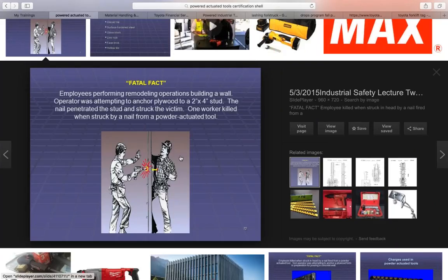Also, ensuring that cranes and hoists are inspected to see that all the components are in good condition, to make sure that they're all compliant, lifting hooks, equipment, whatever the case may be, and then not exceeding the lifting capacity of cranes or hoists. Like we talked about, not only exceeding the capacity, but like I said earlier, anytime we get to the hooks, the slings, the crane itself, whatever the case is, anytime we get over that 75%, like I said, critical lift.